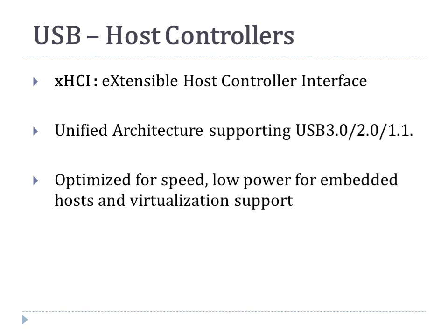And finally, the latest USB host controller is XHCI. This is also developed by Intel, and it is a unified architecture supporting USB 3.0, USB 2.0, as well as USB 1.1. It is optimized for 5 gigabit per second, and it has a lot of power management features, which is becoming increasingly relevant as USB is being used in embedded devices which are battery powered, and energy and power is of utmost importance in those devices. And also XHCI supports virtualization. The same USB port could be shared by different virtual machines running on a server that is implemented using XHCI.